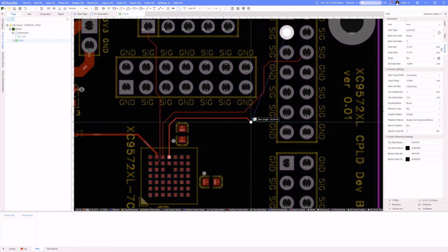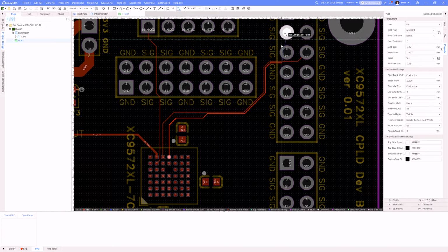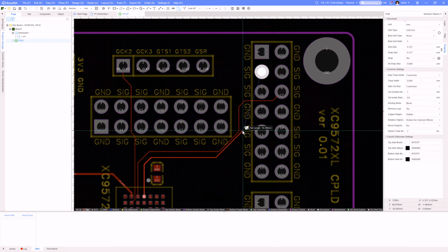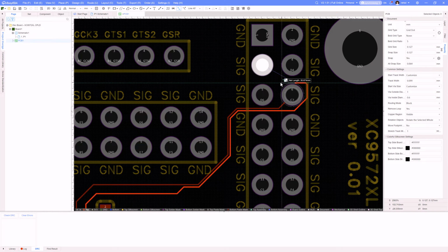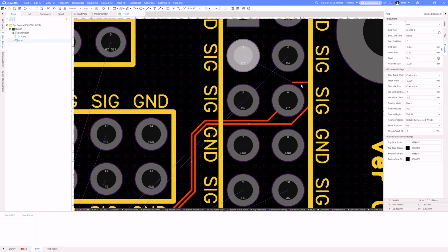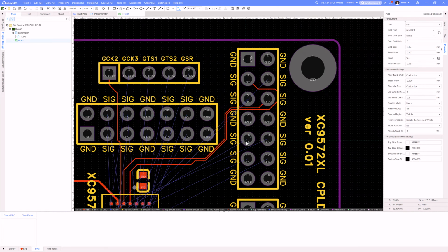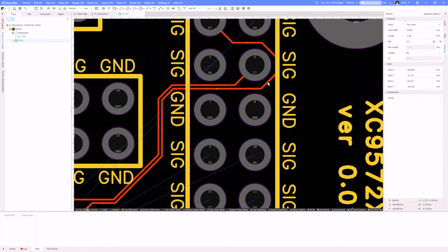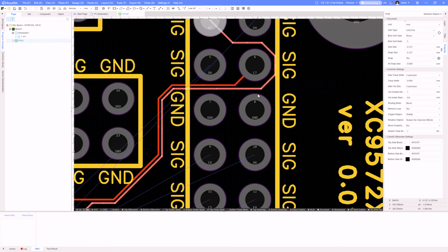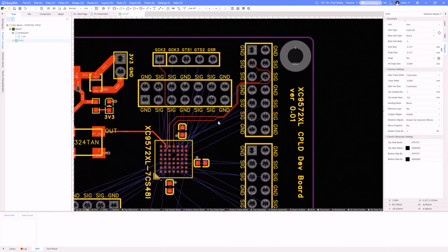Now in this case, I run into a problem right away. It's like, okay, I've got to get that to the other side because I want to connect up to that. So I have some choices. I could do a via and drop it to the bottom. I suppose I could come up here and see, do I have room to run it around this? And I'm sure we could discuss if that's good or bad, but maybe for now I do that and say, okay, connect that there. Again, I can be tweaking these as I go, just trying to find the setup that I think looks best.